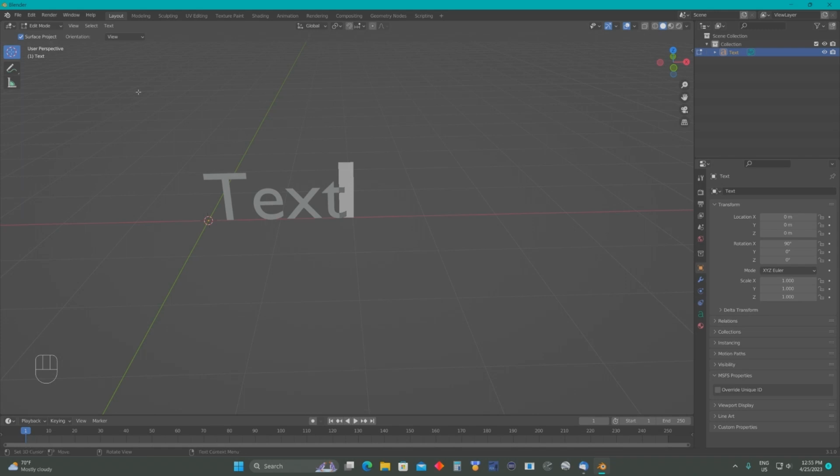One thing about Blender is you want to get the hang of using keyboard shortcuts, because it's a lot faster and easier than trying to look through the menu and find the right drop down menu to do whatever action you want to take. So that's one of the things you have to get the hang of. If you want to go from edit mode to object mode, you can use Tab. If you hit Tab, you can go back and forth from object to edit.